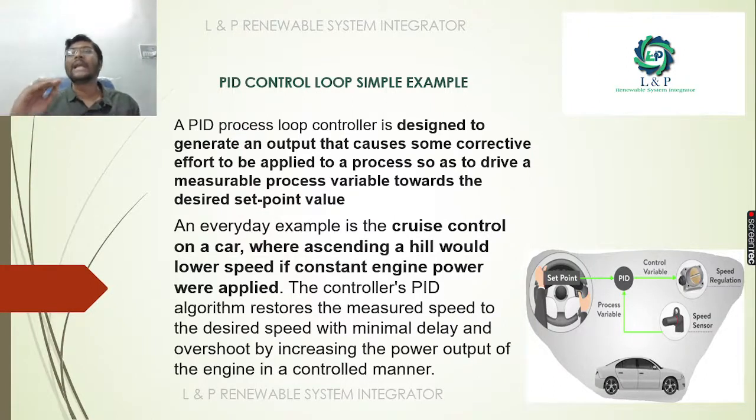Say for example, you are getting a 35-degree or 38-degree temperature, but you had programmed that for a 40-degree temperature the damper has to open fully, 100%. If the 38-degree temperature is maintained for a long time, there is a possibility of it creating a temperature problem. In such places, in order to adjust that 2 degrees, with the help of this PID loop we can establish that. So if you want to create a controlled environment for a heating, ventilation and air conditioning system, you normally go for this PID control loop.